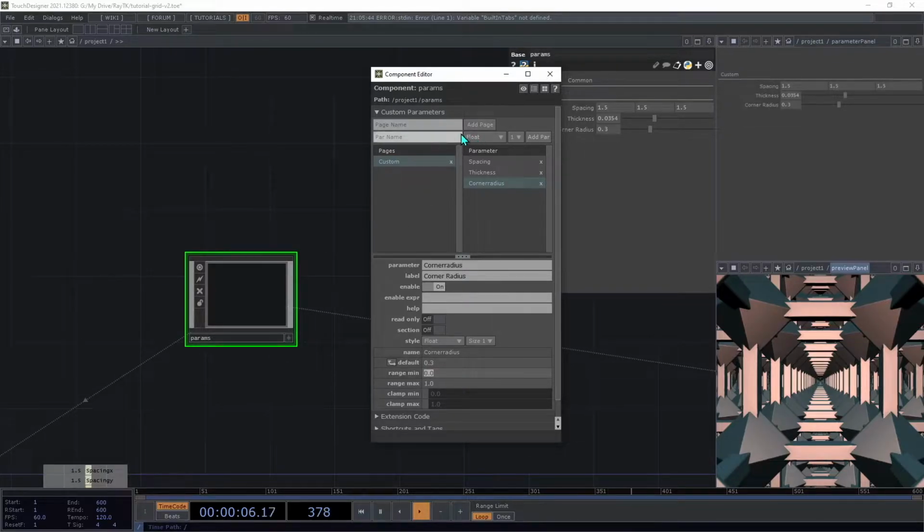We're then going to create another float parameter named stair radius. And this is going to be for the distance that the stair blending applies between the two shapes. Now for this one, we're going to set the default to 0.15. We're going to create another parameter called stair count. For this one, we're going to set the maximum range to 10 and the default value to 6.